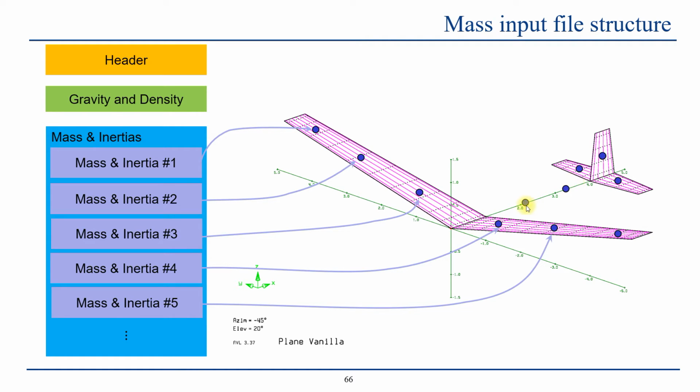But still we do have point masses along the fuselage to define the mass distribution overall for this aircraft. We are not leaving 0 point masses on the body or the fuselage, to be able to capture a proper mass distribution for this geometry. And as you can see, each of these point masses will have its own section or its own line that we will look at shortly, showing how they will be defined as you create your point masses for your geometry file.